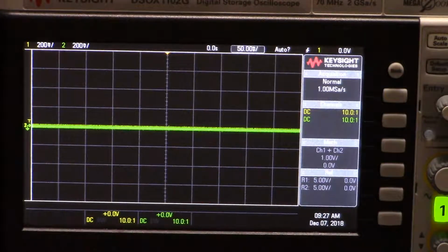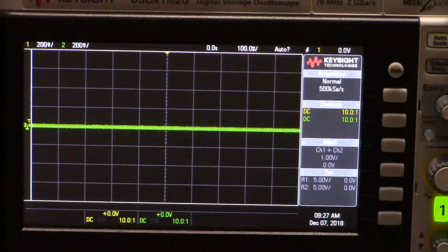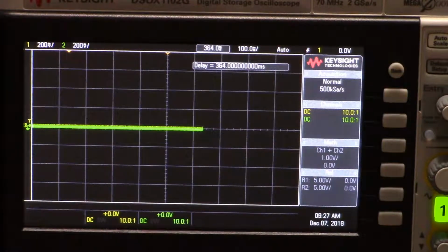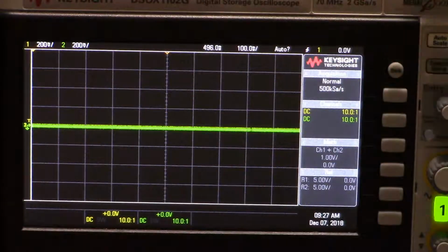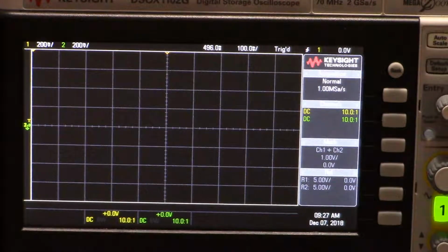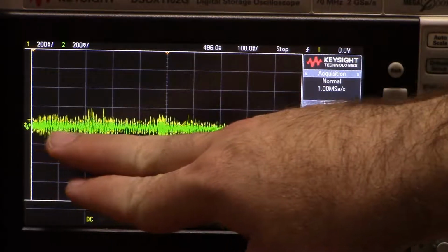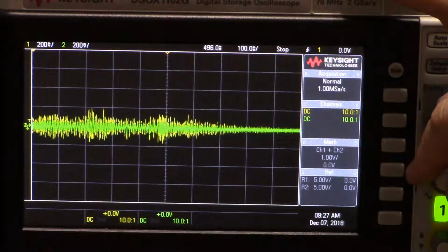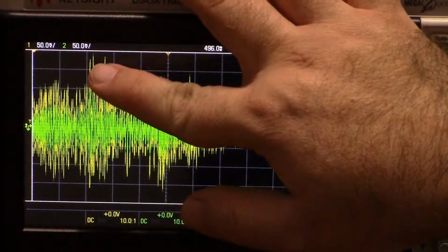Let's see, let's measure 100 millisecond separations will give us half a second, but if I move this over, I move the 0 point, so the 0 point's on the left instead of the middle. So now we're roughly going to get 1 second. So whenever I do single to capture and play a notification sound, you can see that it recorded the notification sound, and I can zoom in a little bit, like this, and I can get an idea of the magnitude here.